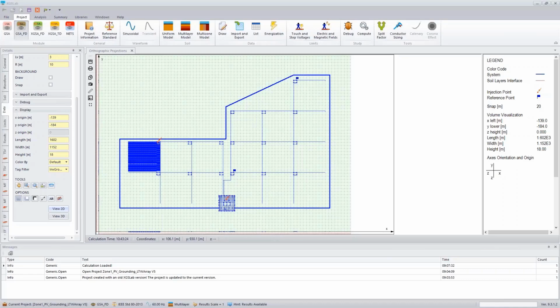But one of them was asking about the system testing for this. So what XGS Lab does is it's a flexible grounding software. You can also evaluate AC interference concerns such as transmission lines next to pipelines, how much induction you may have. It's flexible software that allows you to do complex grounding system analysis for various systems. The more accurate you can be on your modeling, the more you can match reality. And that's our ultimate goal, is to create a virtual twin of what the physics is of a fault and how that's going to translate in your grounding system.